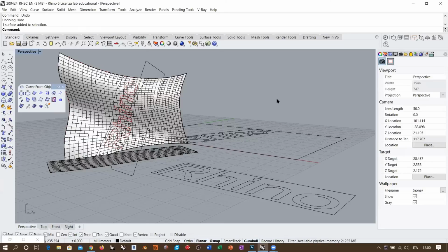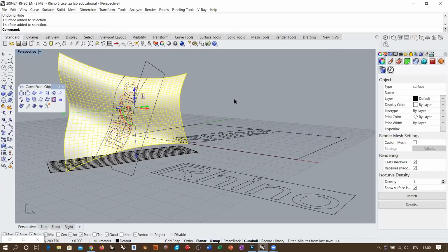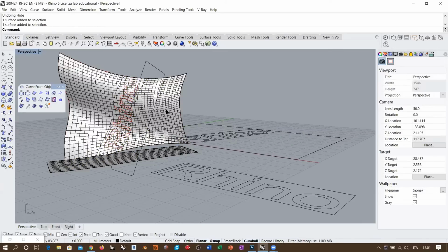The projection is a geometrical operation, while UV curves are a parametric operation. They both can lead to some deformation. But when you work with projection, the deformation depends only on the geometry, so you have no possibility of controlling things. If you work parametrically, you can edit the topologies involved in the process in order to regularize the result as much as you can. But you will always get some deformation.